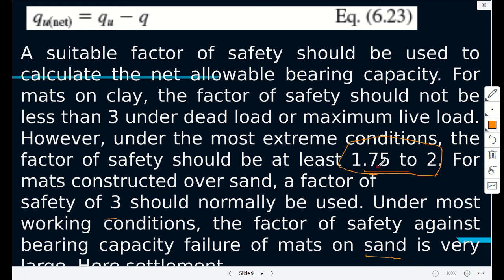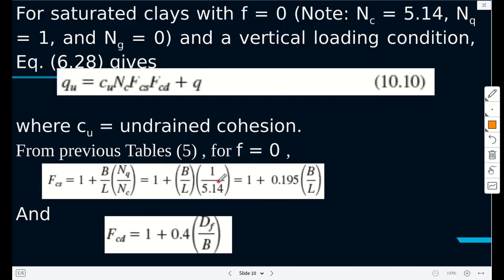If, for example, the soil is stiff and has good bearing capacity, and you're sure of many things, then you can use such low values. However, for foundations, generally the factor of safety is between 3 to 6, and especially in loose sand, which causes problems. So once you determine the bearing capacity, you try to use a reasonably large factor of safety against a bearing capacity failure.